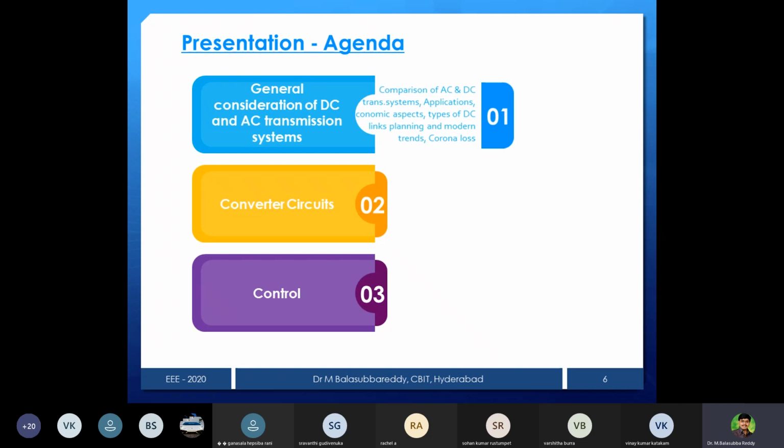But when you are using a 12 pulse converter, another 6 pulse converter is connected in series. Here, once you are using this converter on the transmission side, it is not 6 devices actually. There are 6 units, and each valve has thyristors connected in series and parallel, forming a string.